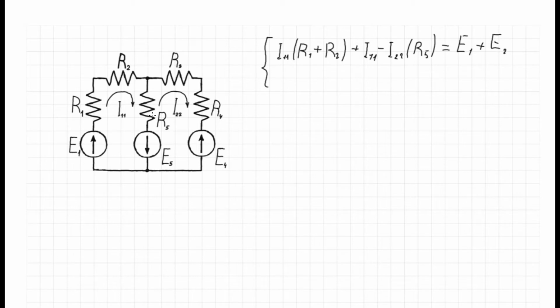As we know from the Kirchhoff law for voltages, we should add the differences of potential one to another around the closed loop: for R5, next R3, next R4, and the voltages of the electromotive sources on the right side of our equation.